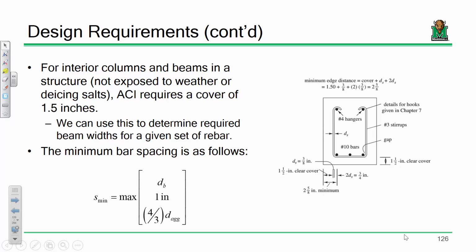So here's a typical reinforced concrete beam. Okay? Let me ask you a question. Let's say I had a beam that was 6 inches wide, and I said I was going to put 12 number 14 bars in one layer in that beam. What would you say? If it's 6 inches wide, and I'm going to put 12 pieces of rebar that are number 14s. You're shaking your head. Why? It's too much area. It's too much. It's not going to fit, right?